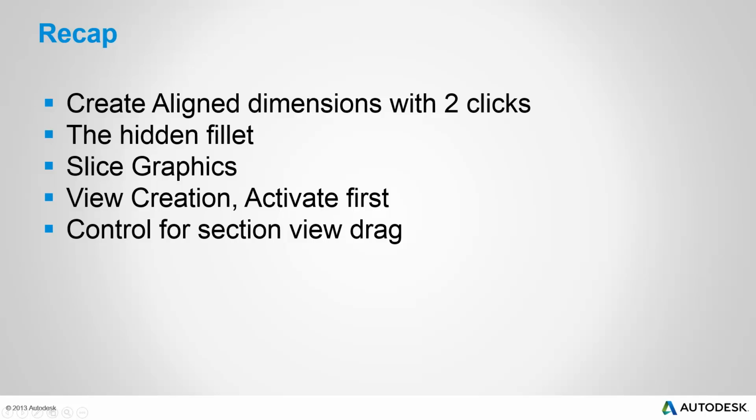We also showed you how to turn on an additional fillet type in the plastic part category. And this fillet is a ruled fillet, which allows you to have a new process for how you can create fillet geometry as opposed to the standard fillet that you might be used to using. I think this is very powerful and something that you should explore the benefits of.